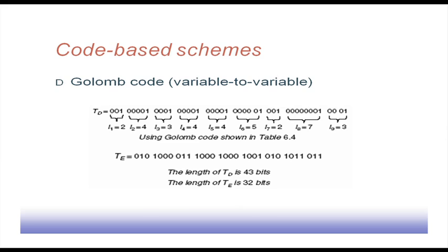zeros. And sometimes there is another modification where we consider both run lengths of 0 and 1. So, there has to be another bit which will do this complement from 0 to 1. It tells whether it is a run of zeros or a run of ones, and then the run length. If that is done, then also there will be saving when we are looking into the coding.